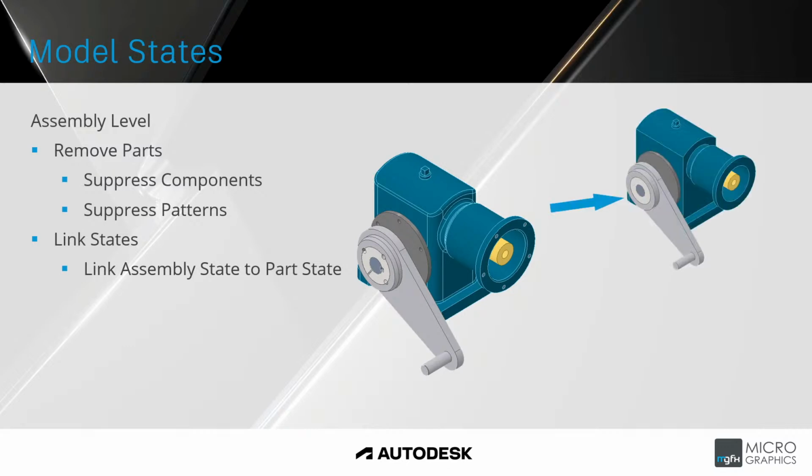So if we have a look here, from the left to the right hand side image, we can't really see it here, but there are internal components that have been suppressed within the design. But at the same time, there are states that are linked. The original assembly has 3 states: fine, medium, coarse, and those states are linked to states within each of the components. Each component has a fine, medium, and coarse state. So when the assembly is put into the medium or coarse state, the components also change.